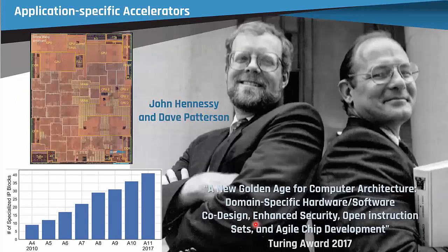In 2017, yes. Because, okay, how does it help us keep the temperature down? It doesn't put the temperature down, it keeps the temperature constant. We know there's a wall at which we can cool down chips. We can cool down a chip in your laptop at a few dozen watts, in your desktop computer at 100, 200 watts, in your servers, I don't know, up to 400 maybe is crazy, right? We can't go over that. But if you don't raise the frequency, you're not raising the power density.